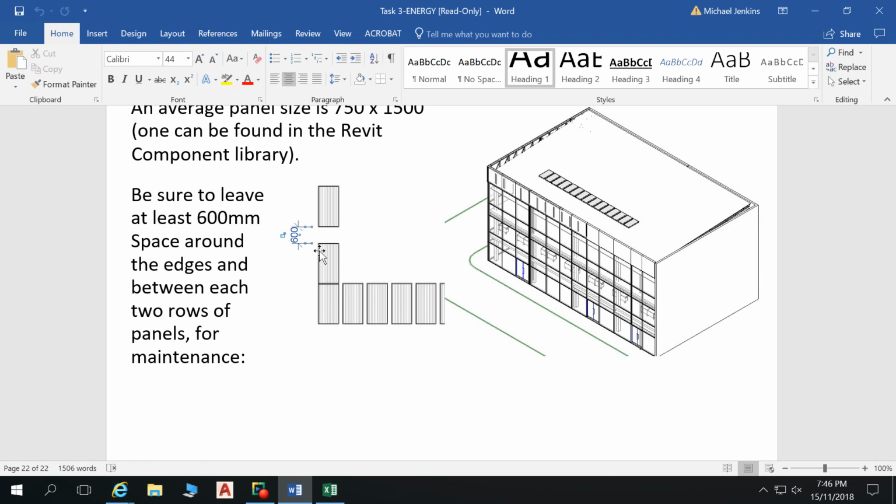So yes, you can install a bank of panels and then another bank of panels like that. But if there's a problem with any of those panels later on, and you've got a bank that's 5 panels deep and you've got to get to one of them in there, that means you have to take off a whole series of panels to get to that one that's further in.